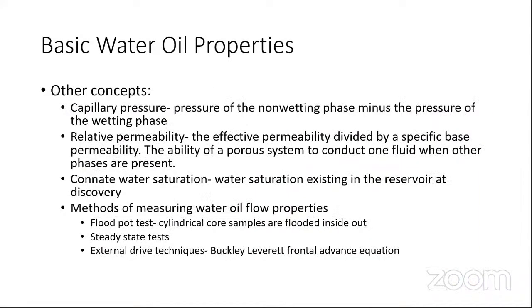Other concepts for your basic water oil properties are capillary pressure, the pressure of the non-wetting phase minus the pressure of the wetting phase. Then relative permeability, which is the effective permeability divided by the specific base permeability, so the ability of the porous system to conduct one fluid when the other phases are present. Then you have connate water saturation, the water saturation existing in the reservoir at discovery. And then you have methods of measuring water oil flow properties. You have a flood pot test, where cylindrical core samples are flooded inside out. You have steady state tests. And then you have external drive techniques, which is the Buckley-Leverett frontal advance equation.